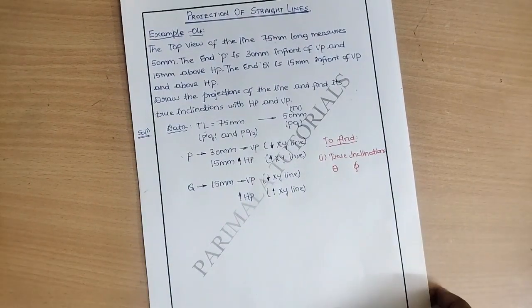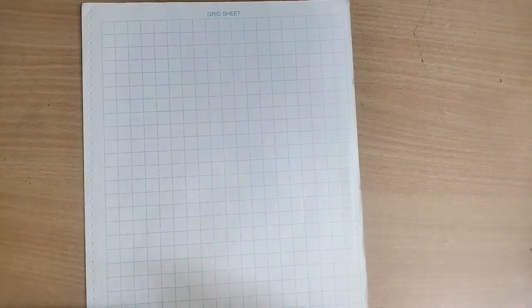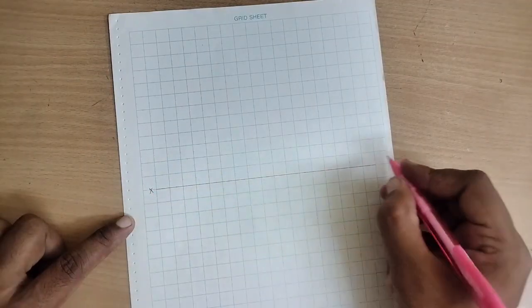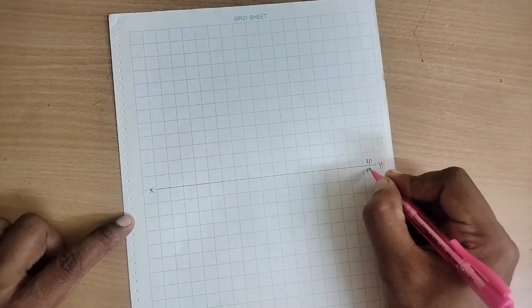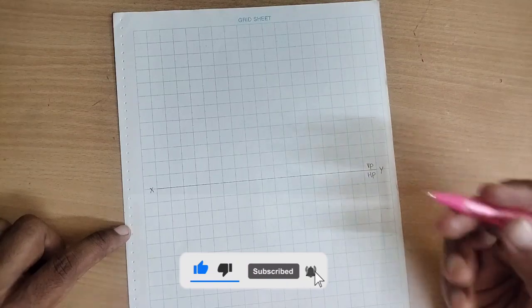Let us see the solution. I will be making use of grid sheet for the solution. So this is the grid sheet. The grid sheet clearly says that 1 unit is equal to 10 mm. Each block is 10 mm. First thing is, I will draw the XY line. With this XY line, I will call one end as X, the other end as Y, and let us mention it as VP and HP. So this VP HP indicates that projection of straight line is in the first quadrant.